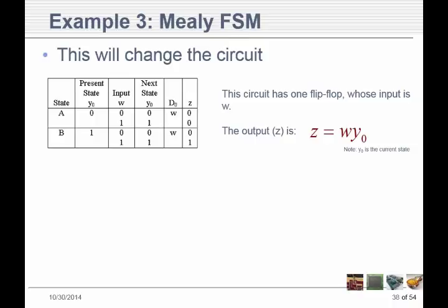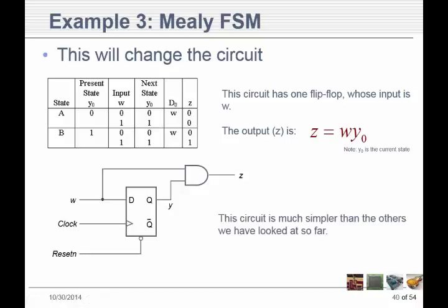I mean, this is what makes it a state machine. You have that part of it that it has to remember. In this case, it had to remember that there was one W that was here, and we're looking for the second one. And when we see the second one, then we can let the output go high.